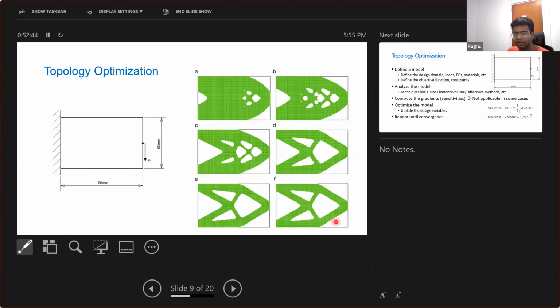So this part can be manufactured using additive manufacturing, 3D printing, many such things. I mean, sometimes conventional methods of manufacturing are also possible. So this is roughly how topology optimization works. So we compute the stresses, and I said sensitivities in the first slide, right? We slowly push the ball. We slowly change the value of W.